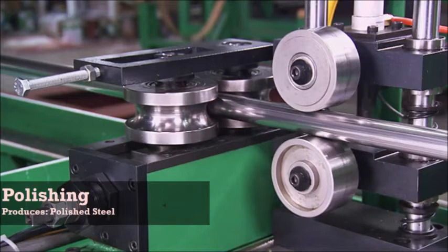A mechanically polished surface yields an abundance of scratches, strains, metal debris, and embedded abrasives, and always distorts the metal surface. Burnishing metal by lapping or buffing decreases the micro-inch roughness and improves the image-defining quality of a surface, but it never completely removes the debris and damaged metal caused by polishing. After the process, it produces polished steel.